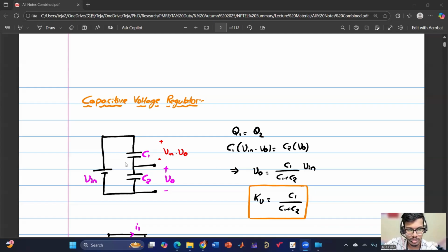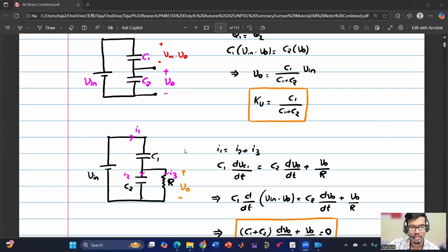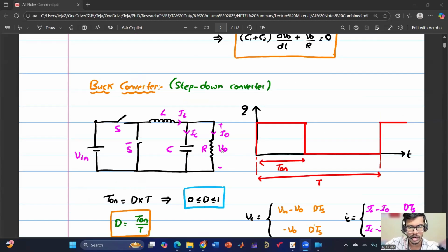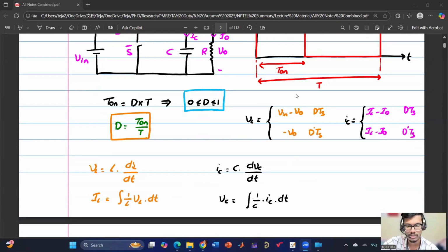So now what you can do is get the voltage expressions of the capacitors when the switches are in one configuration. The moment they are converted to another configuration, again you have to solve for the capacitors based on this charge balance and then see what the output voltage is. In a practical converter, the capacitors will charge and then reach steady state. But ideally, it will happen instantaneously.